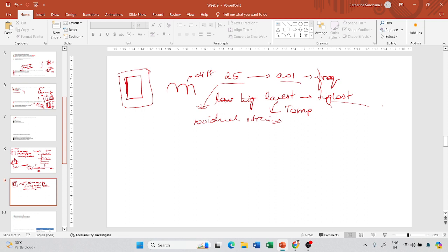So what will happen if it has irrecoverable strains? If you do it on the same sample, it is going to affect the subsequent values for the loading that you keep on applying, right? So you should first start with the frequency or temperature at which the material response strains are recoverable. If even at the lowest temperature you are observing an irrecoverable strain, you should change the sample.